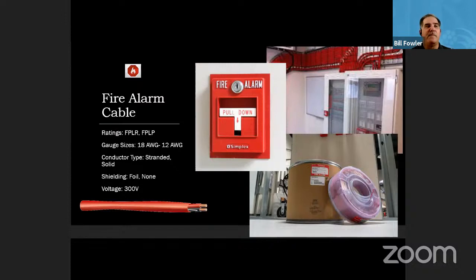The nice thing about the barrel is that with those multiple footages, if you've got a really large building, let's just say a warehouse, where you have really long annunciator, indicator runs, typically go up to 1,200 feet, and those are daisy chained. So a lot of contractors like to pull one wire the whole length, and they will come along and tag the strobes along that. Well, your reels were 1,000 feet, so you ran short, and you had to take another spool and get that other 1,200 feet out.